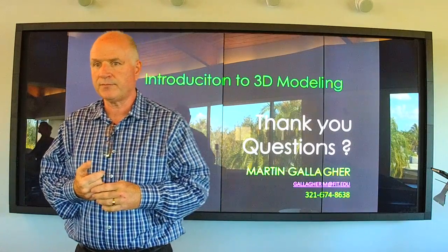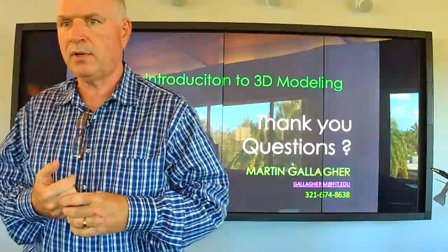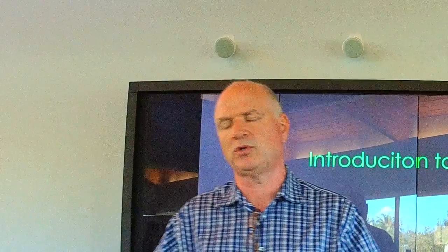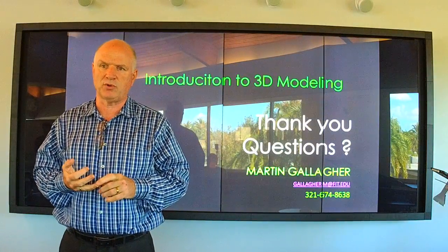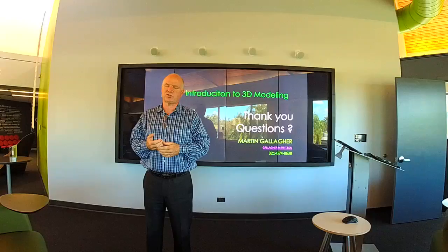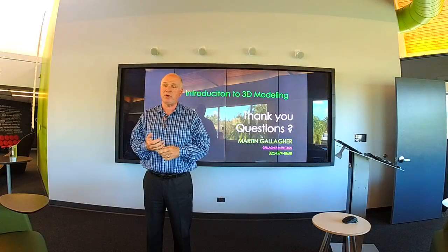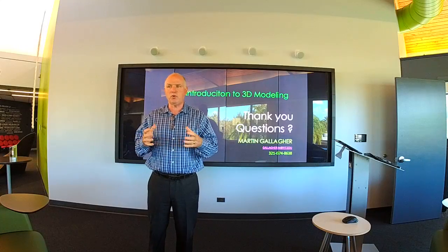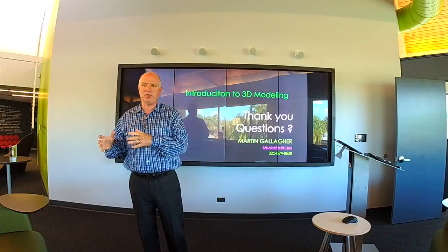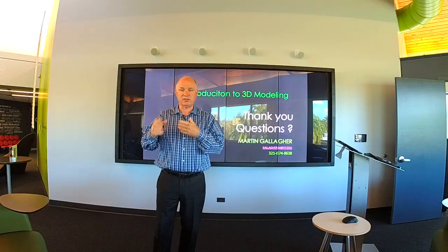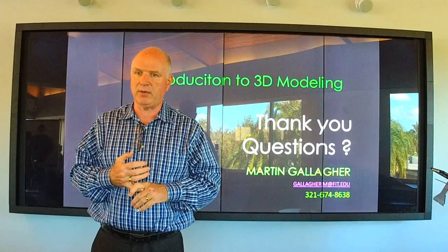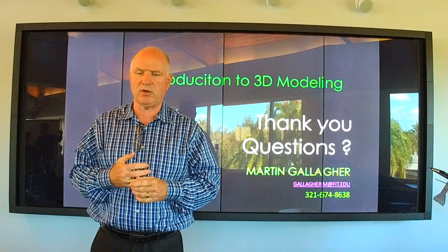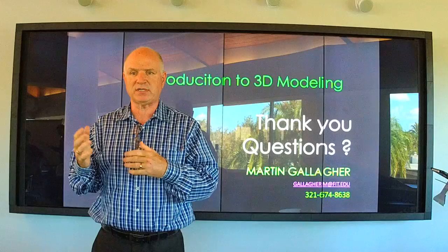Yeah, I'm asking about the requirements for a laptop that can support. With SolidWorks for instance, it wants about 8 gig of memory, a decent i5 or equivalent processor, and a lot of storage space. The more memory, the better. If you've got 16 gig, anytime you're working with modeling files, you want as much memory as you can, because those files can build up very quickly if you're doing complicated models. So minimum spec for SolidWorks is 8 gigabytes of memory, and probably an i5 or equivalent processor, or anything faster than that will be better.